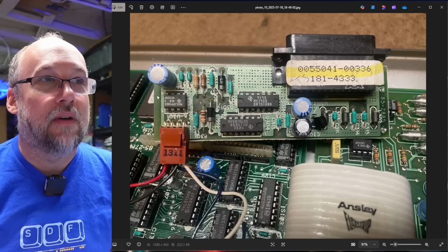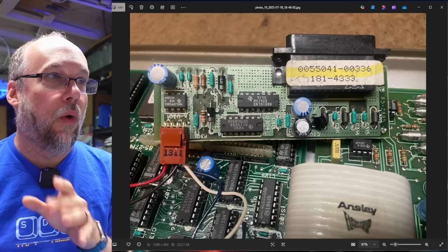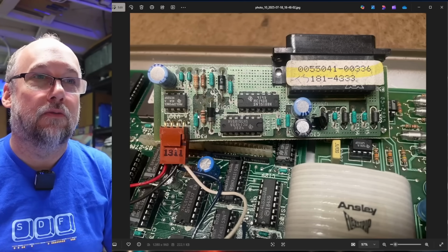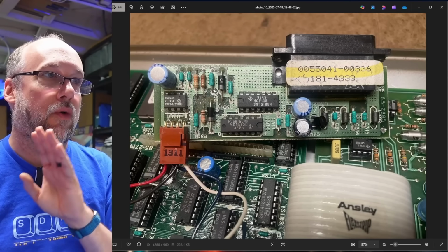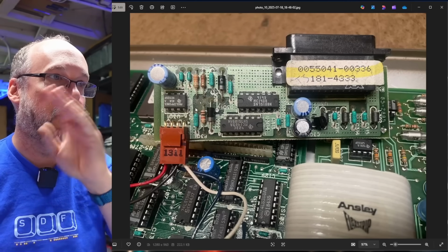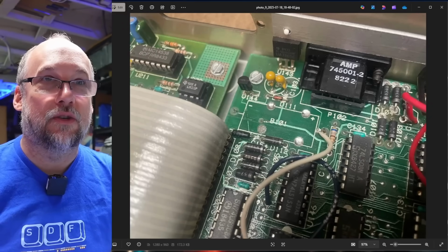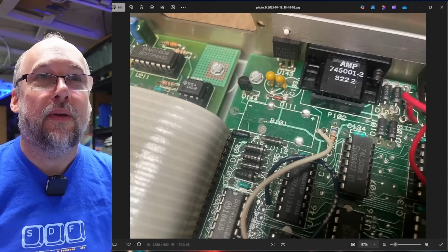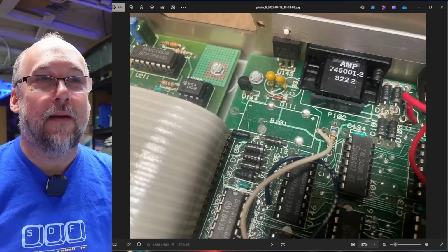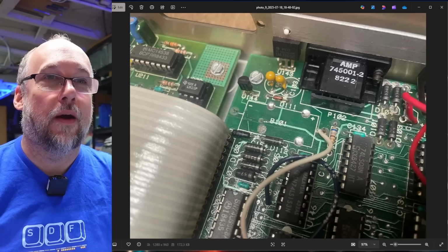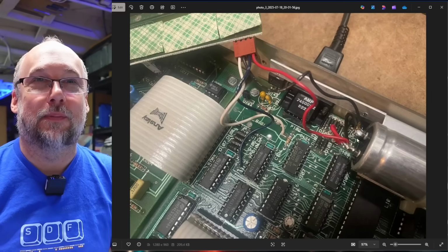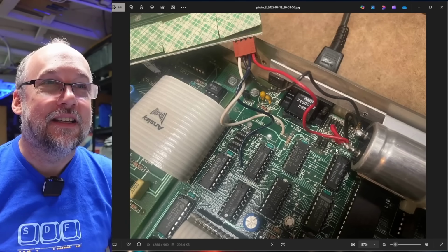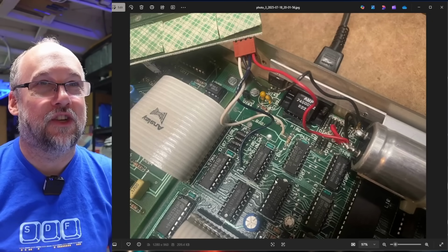And it's using this 555 timer to convert the 12 volts because it's actually picking the power up directly from the large capacitor, and that generates the minus rails that are required for normal RS-232 because normally it swings into the minus range. And when it comes to the actual serial connection, it picks it up from that pin right next to where the battery is and that pin next to this IC. That's it. These two wires are for serial, receive and transmit, no flow control. And the serial board is picking up its power directly off the capacitor. It's so hokey the way this is bodged in.